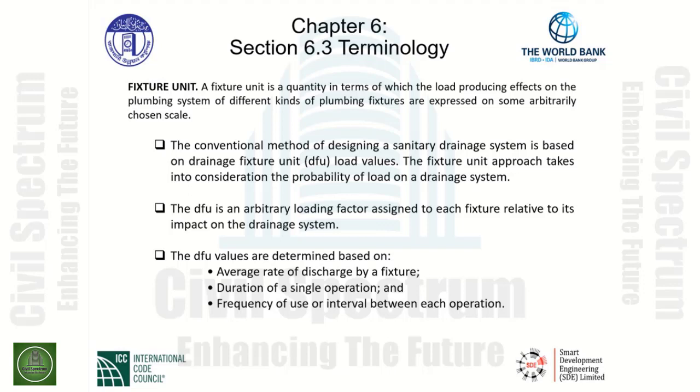The conventional method of designing a sanitary drainage system is based on what we call drainage fixture unit load values, abbreviated DFU, or simply fixture units, which can be used to define this particular loading probability.